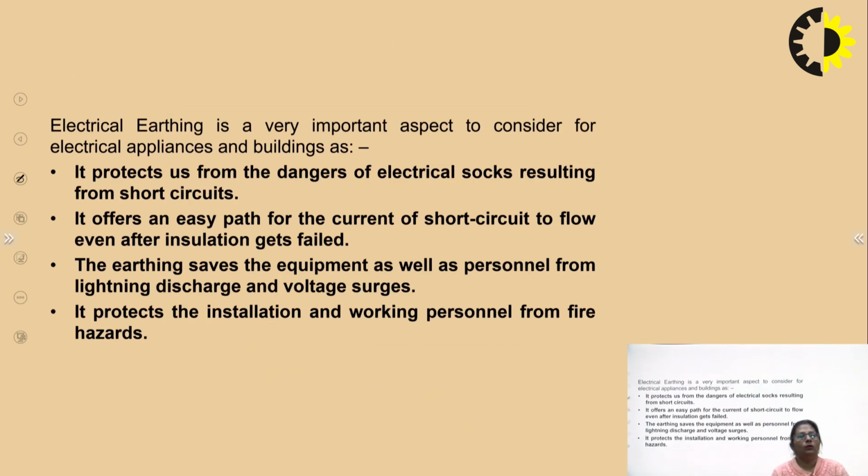Now, why is earthing required? What is its importance, right? When it is considered for an electrical appliance, for any installation, or for any building, it protects us from the danger of electrical shocks resulting from short circuits or even overloads, even unbalance, because one of the ways of earthing is also neutral grounding.